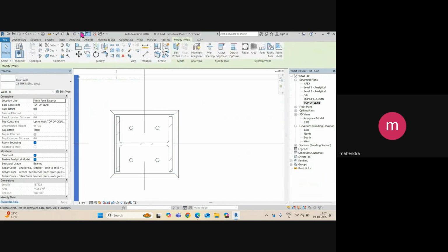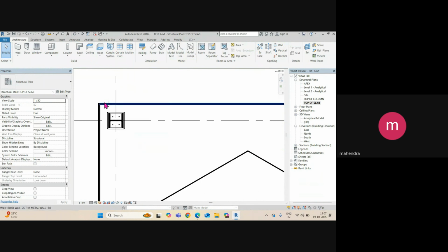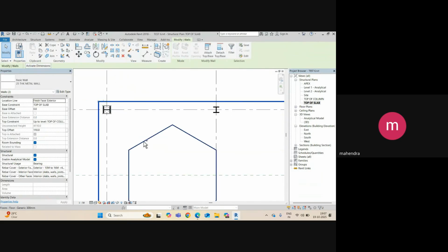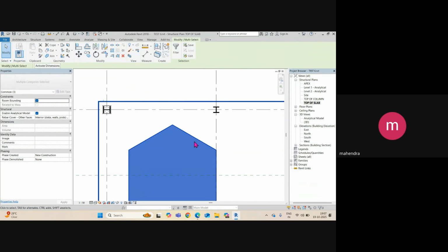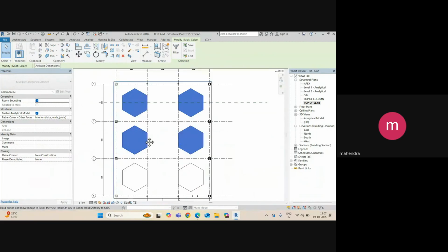So I want to show only this steel member. Okay, the remaining concrete members I want to show in half tone, means you can say in faint, because in this drawing I want to just give the information for the steel structure. So you can select all these concrete items here.